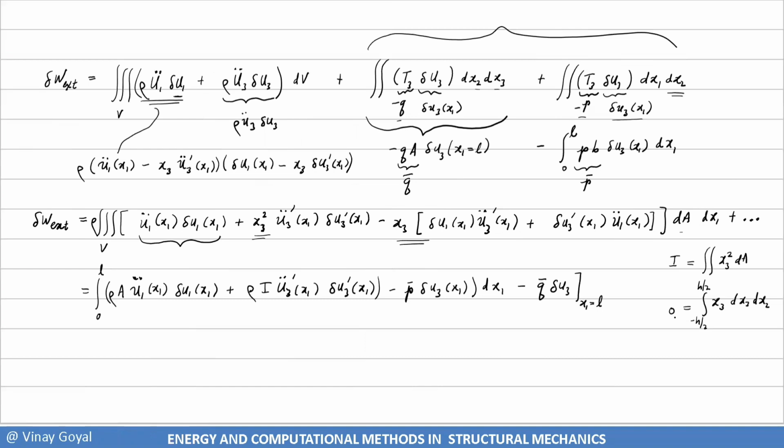I'll basically propagate it here by putting a minus there, and there should be a minus there, and there should be a minus here. So I apologize for that. And there's no body forces in this particular example. And now I'll use the principal of virtual work to set internal virtual work equals external virtual work.